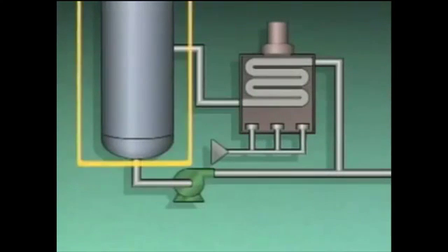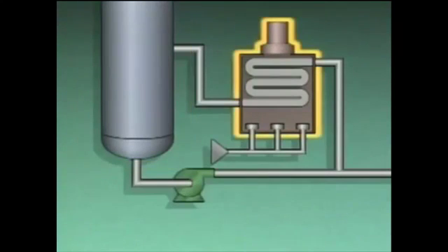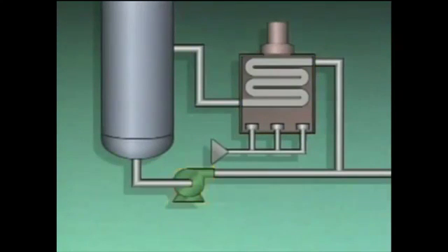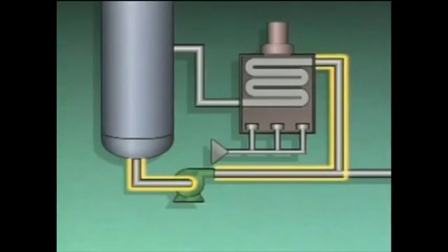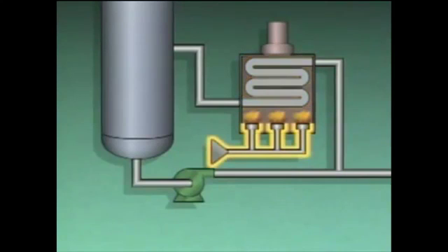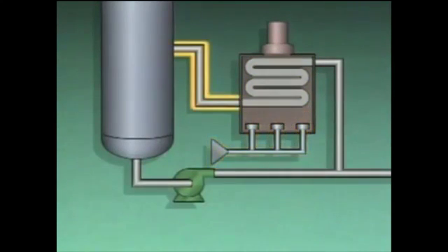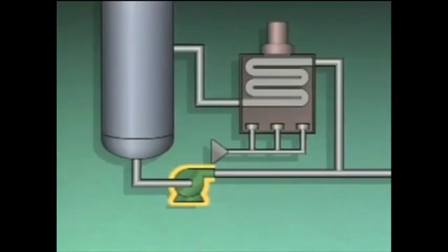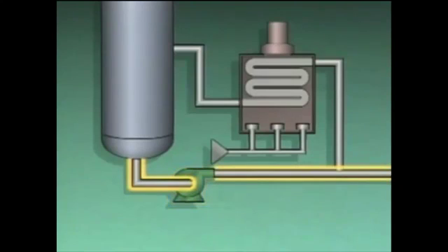It includes the bottom of a distillation tower, a fired reboiler, and a pump. During operation, part of the liquid from the bottom of the tower is pumped to the reboiler, where it is heated by the burning of fuel in the furnace and its lighter components vaporize. A mixture of the vapors and any remaining liquid is returned to the tower, where it provides heat for the distillation process. The pump also moves part of the liquid from the bottom of the tower to storage or to other processing equipment. This liquid is the tower's bottoms product.